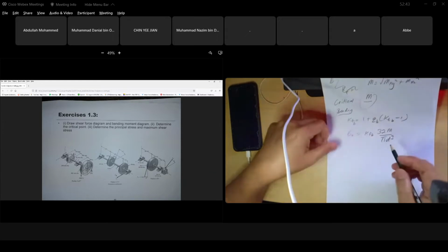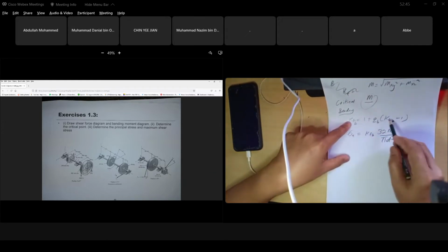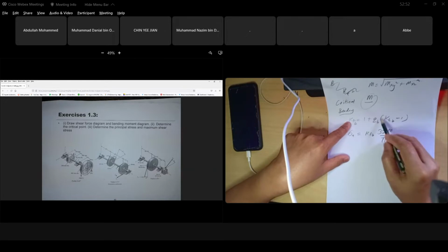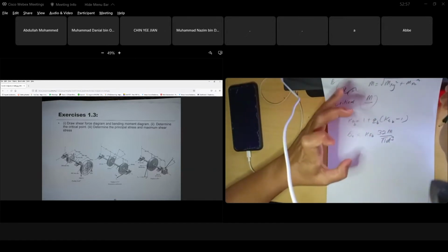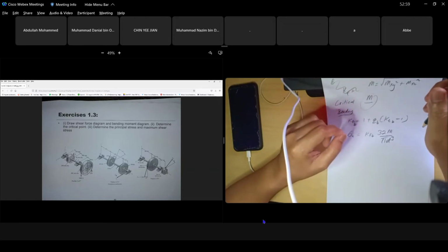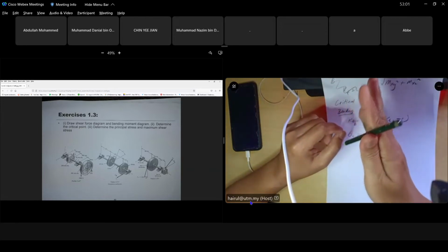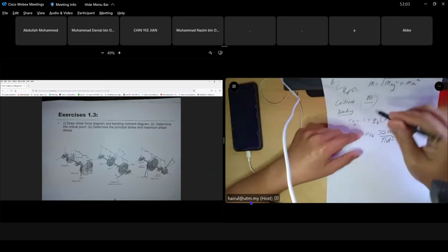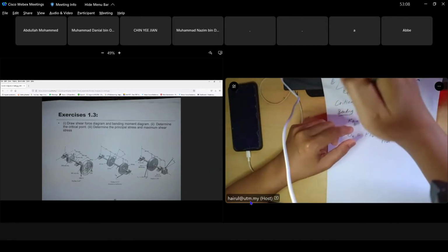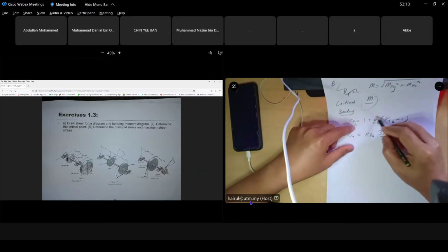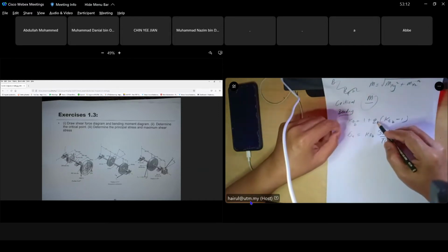If KF bending is not given, you have to find it manually from chapter 4 for KT. Q bending is from chapter 8, notch sensitivity. Be careful, your SUT is in KSI, so just look at the KSI value. For notch sensitivity we have two zones: one for torsion, one for bending and axial. Bending and axial are the same zone. Check your SUT value.